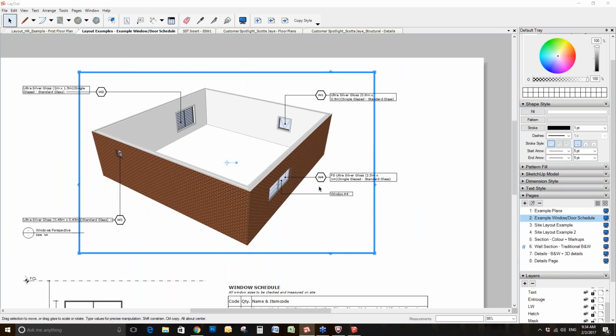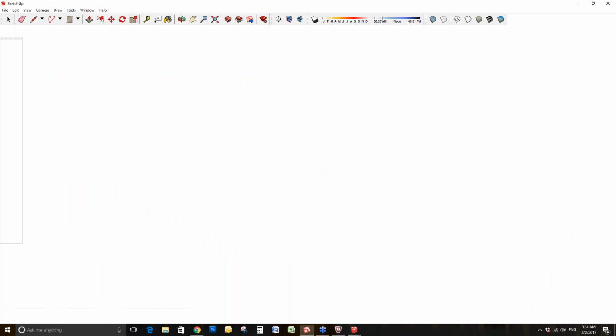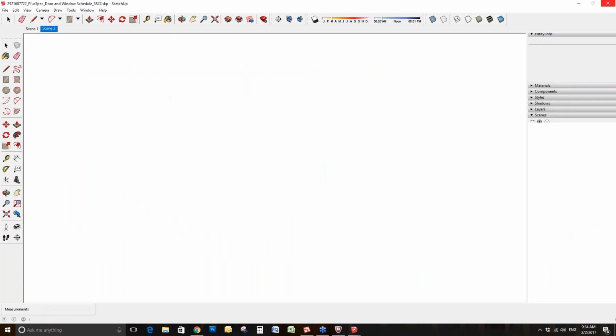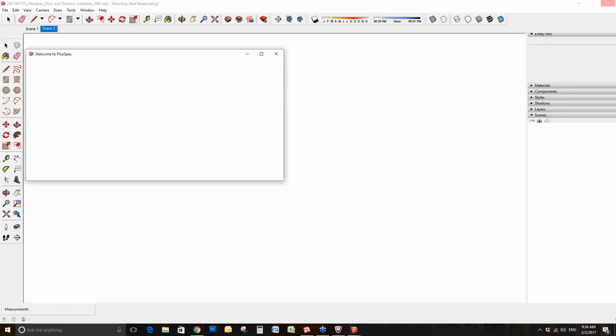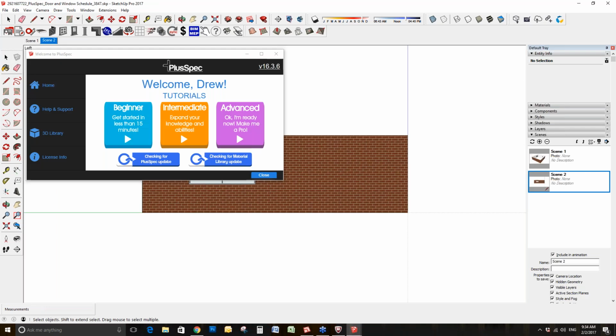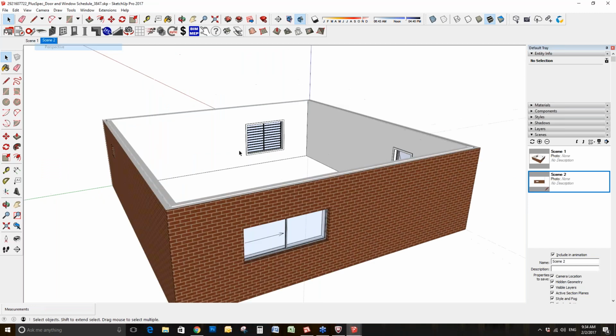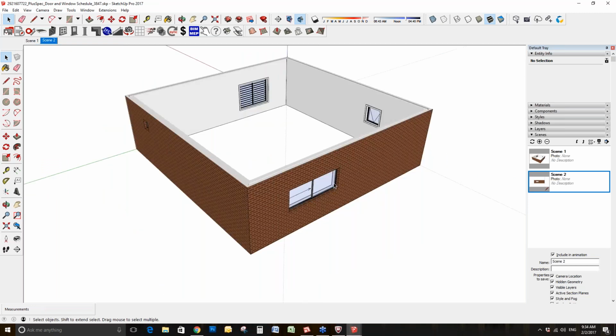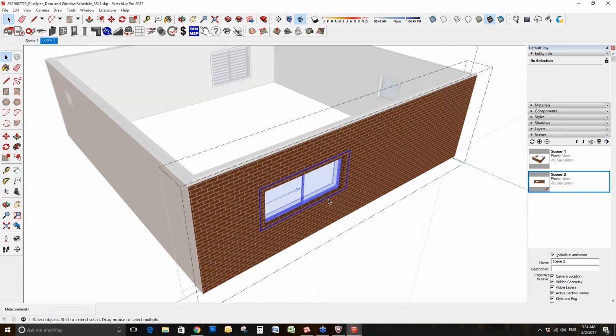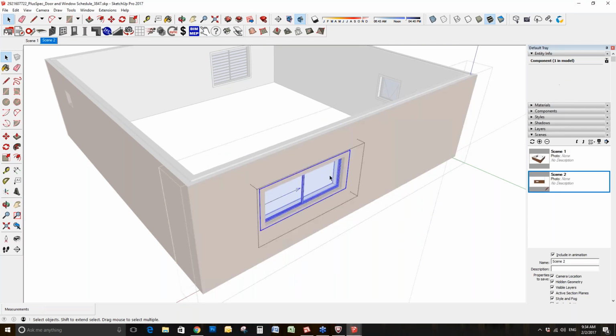I'm going to open it in SketchUp, and I'm going to show you how information is captured so that you can smart annotate in Layout, and that's a really key feature. It saves you so much time. Here's the model. Let's go into perspective mode. If you keep on double clicking into a group, every group, as long as you've got the entity info, will tell you what it is. If I keep on clicking, it's going to start to see what it is through definitions and instances.